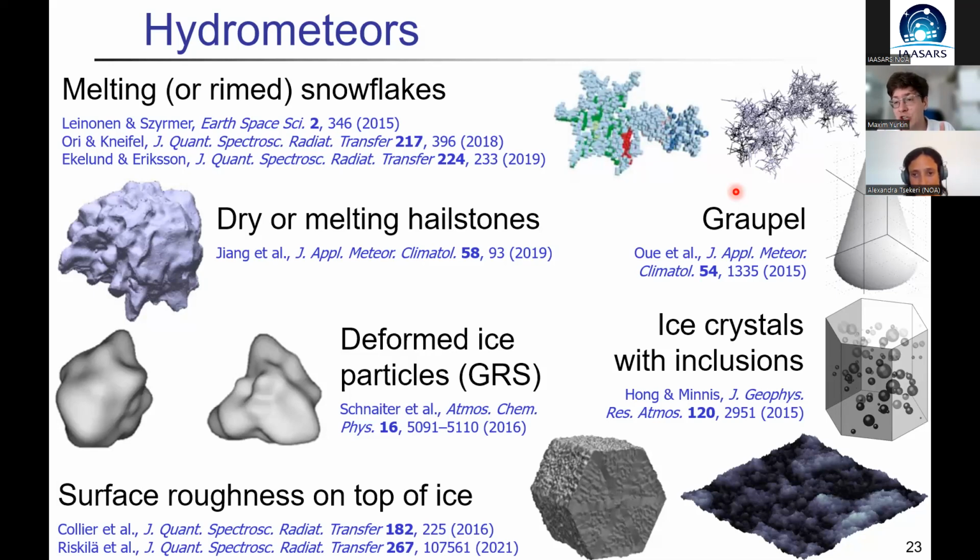But it's not just that it's a large real part, it's also the absorbing part. That's more what I called extreme in the conclusions. It's not necessarily that the iterative solver will break down, but it's more when you will worry about the accuracy. The iterative solver will converge, not fast, but still converge, maybe 1,000 iterations, something like that. But then you will probably need to use very fine dipoles. Not 10 times smaller than the wavelength as we usually do. Usually it's 10 or 15 times smaller than the wavelength, but in some cases you need to go to 20 or 30 dipoles per wavelength, especially if you're interested in backscattering. I think there were some papers where they specifically studied the accuracy of backscattering for these water-containing particles at microwave.